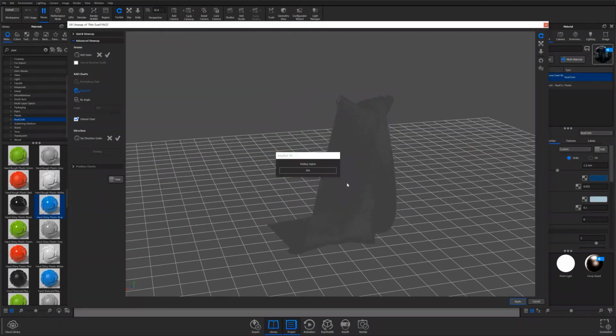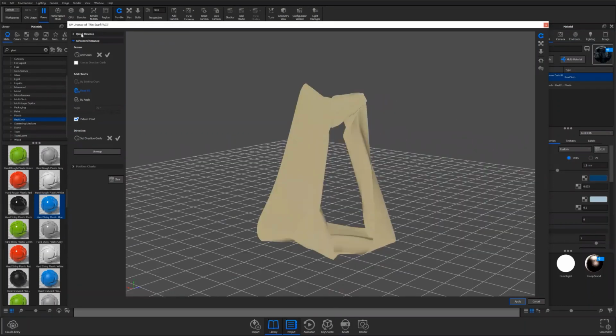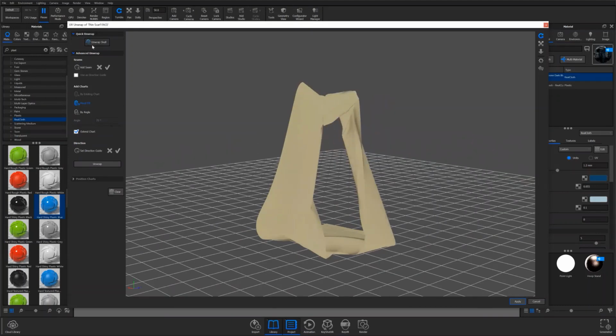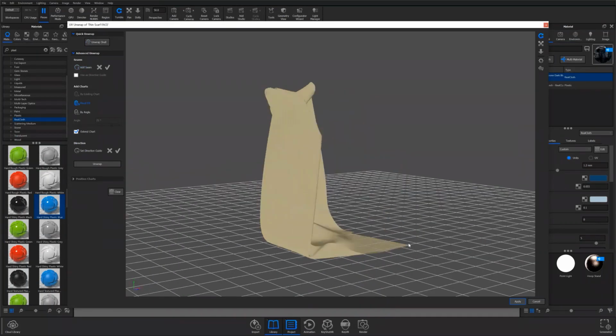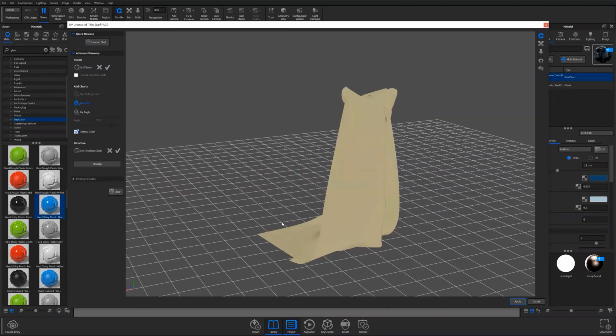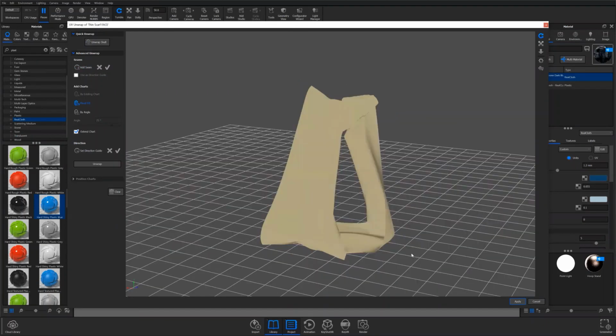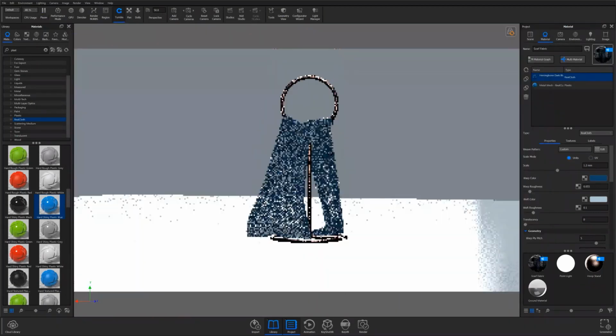This allows you to do a quick unwrap, in the top menu, where we automatically calculate what the UVs should be. That works a lot of times. Sometimes for more complex scenes, you'll need to manually go through and do the unwrapping. In there, you can add seams and do a flood fill, and then manually unwrap that. As Kareem mentioned, there's a good YouTube video explaining that in more detail. For all of our features, you can dig in on our YouTube channel and get more detail.